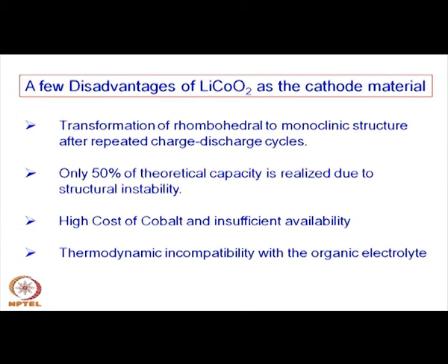But there is a certain amount of thermodynamic incompatibility. It is working for the time being, but if you look at the thermodynamics, the electrolytes are not that stable with either the anode material, the graphite, or the cathode material, lithium cobaltite.